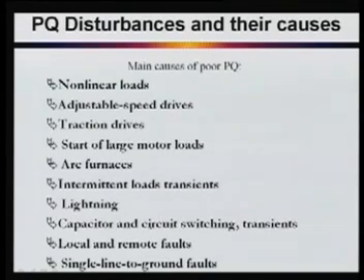But what are the major causes of poor quality? First one is nonlinear loads. Now what are the nonlinear loads? All the power electronics driven loads, either power electronics like converters, if your load is fed through converters, or any other like arc furnaces, they are nonlinear loads. And these nonlinear loads create a lot of problems to the power quality. So nonlinear loads are one of the major causes.